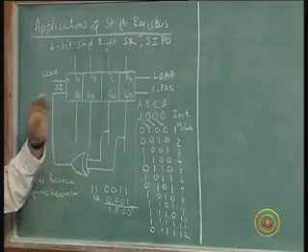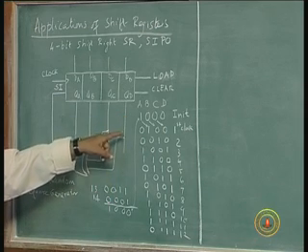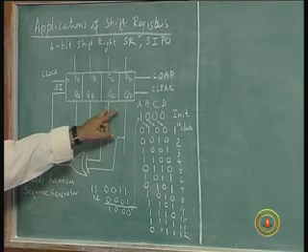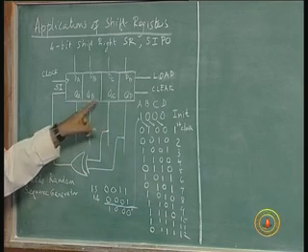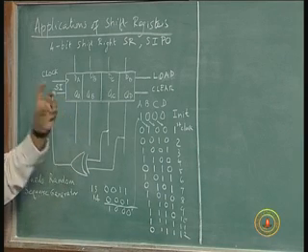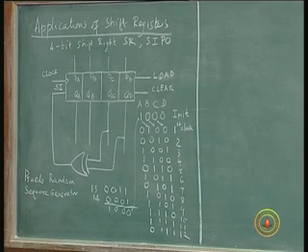And I can now have different starting values, so that the patterns will be repeated, but not in the same sequence. Or I can tap, instead of here I can do here, I can take this and this, and exclusive OR of 3 inputs, I can do all sorts of variations, I can get different sequences and different patterns. So, I can have a simple test design.